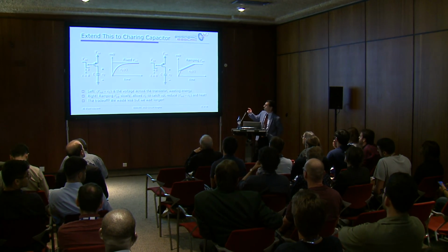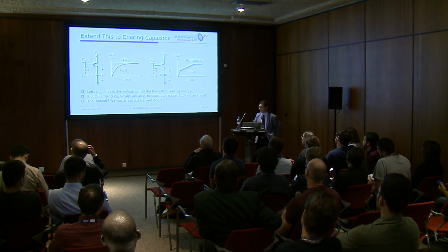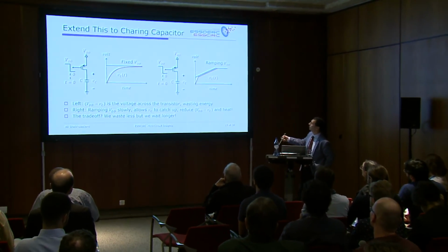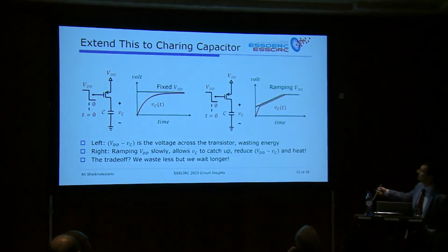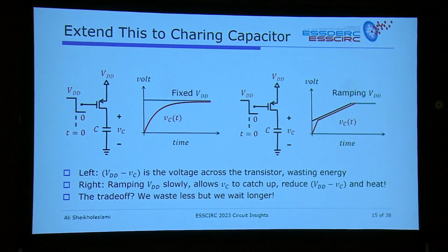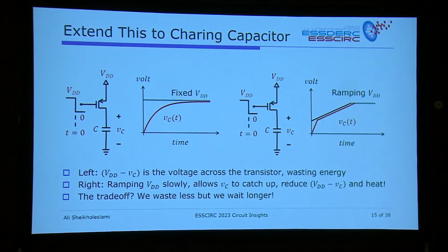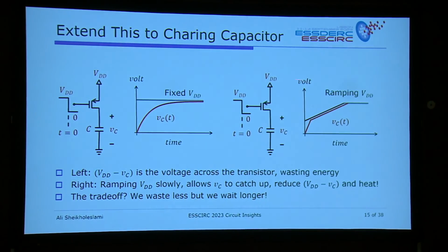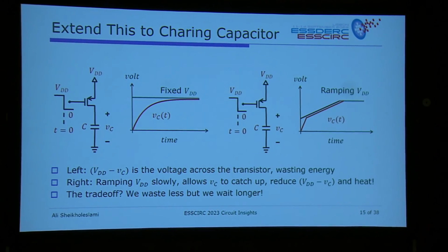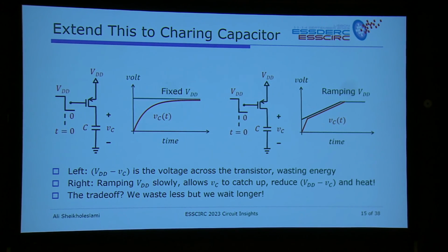This ramping VDD, so this is the one you're talking about? Yes. So what I suggest is that if you can devise a circuit that could have a ramp-up voltage, and what you're asking is whether there's energy associated with the circuit that needs to do the ramp-up, correct? Yes. Yes, there is some in it, but if you design the circuit carefully, and this has been shown, you do not lose half of the energy, you lose a lot less. So, again, this goes back to the previous question, how far does it go in your analogies and your method?